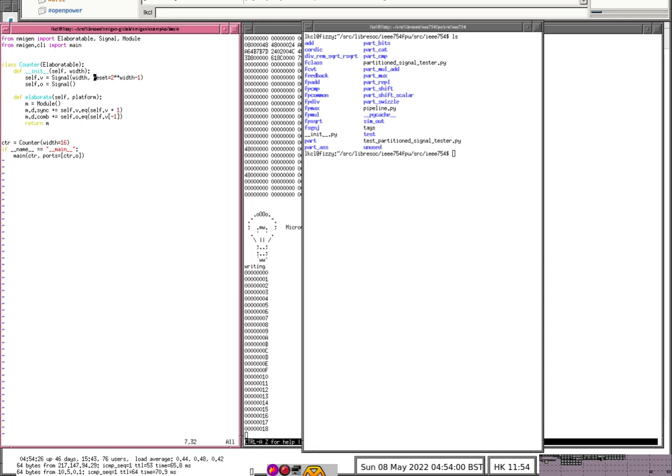One of the main problems of Verilog is that you can miss things and end up with non-deterministic code because you forgot to set the reset values. One of the key things in nmigen was that the behavior of the outputted Verilog should be deterministic. Consequently, every signal, which is a class, has a default argument for its reset, which will be 0 unless otherwise specified.